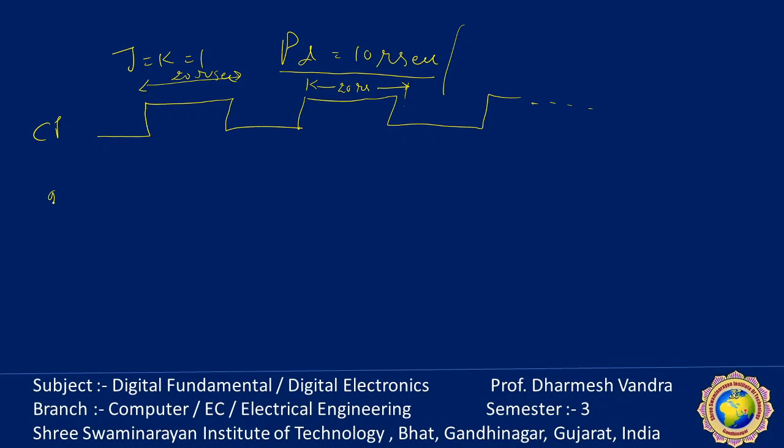What happens if Q is equal to 1? First it will become 0 in this condition. After 10 microseconds, the value of Q is enabled again, so Qt+1 changes again and it becomes 0, from 1 to 0. After 10 microseconds the input changes, but since the clock pulse is disabled, the output remains the same.